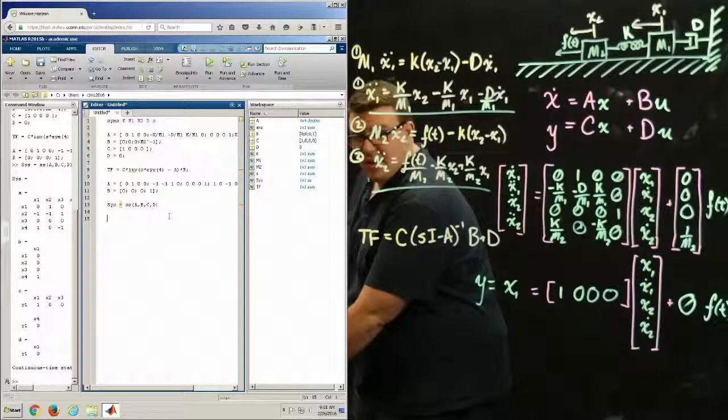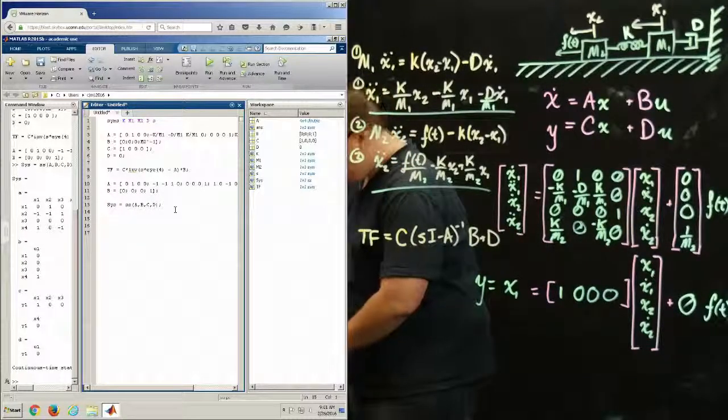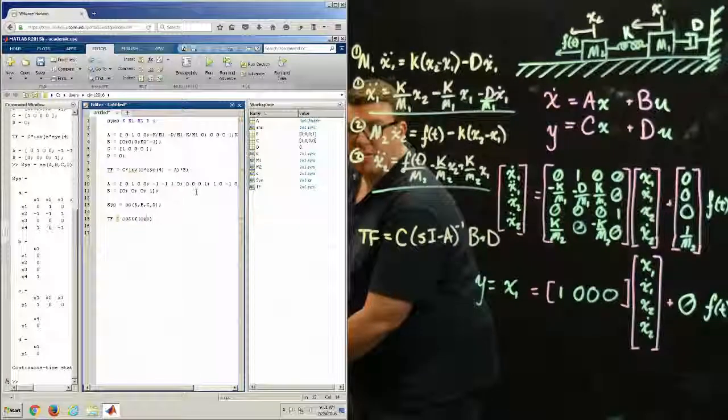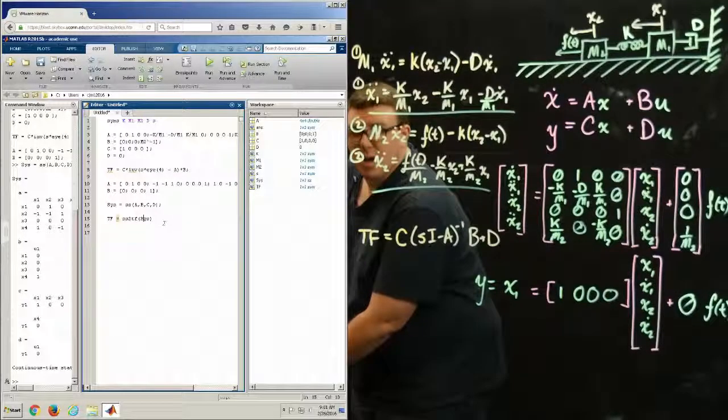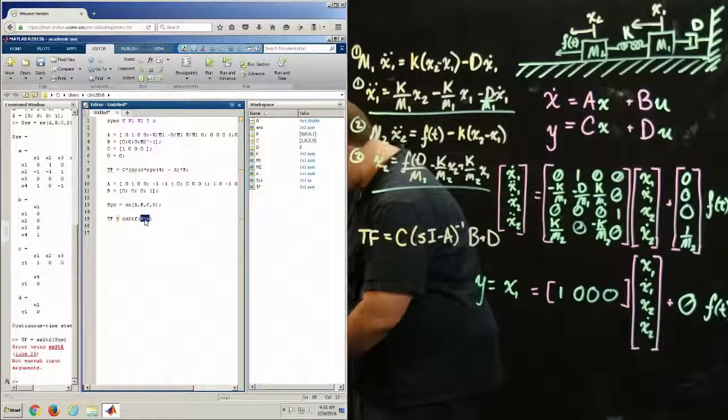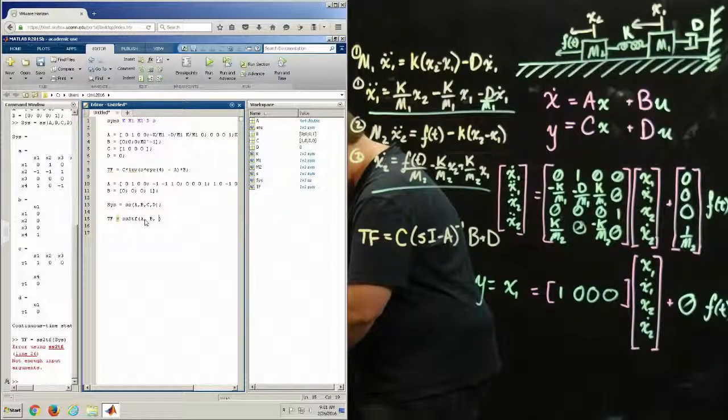And so the last thing I want to show, which is nice, is that you can then take the transfer function of this, so we'll just redefine TF again to be SS, or state space, to the number 2, TF, so state space to transfer function of the system, sys. And there was a capital S. And so if we execute this, oh, not enough inputs. Oh, okay, so it wants state space to transfer. So apparently you don't need system, you just need A, B, C, D.